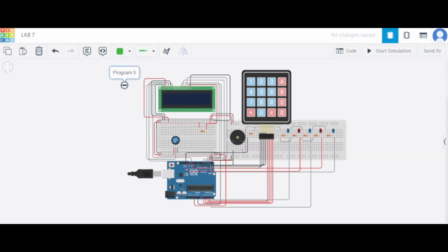To set up the LCD keypad video game with tone rendition, gather these components: Arduino Uno, 4x4 keypad, 16x2 LCD with I2C module, 3 blue LEDs, 2 red LEDs, piezo buzzer, 220 ohm resistor, breadboard, and jumper wires. Use Tinkercad to plan the circuit layout by adding the Arduino Uno, keypad, LCD, LEDs, buzzer, and resistors, and connect them on a breadboard to simulate the actual circuit.